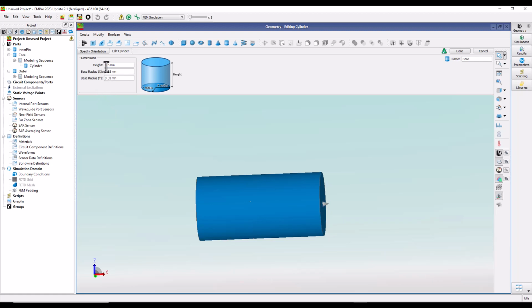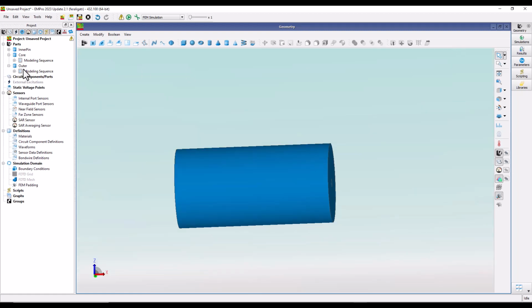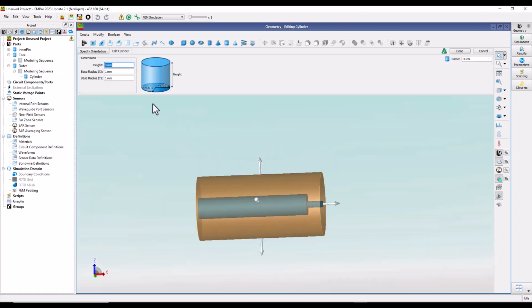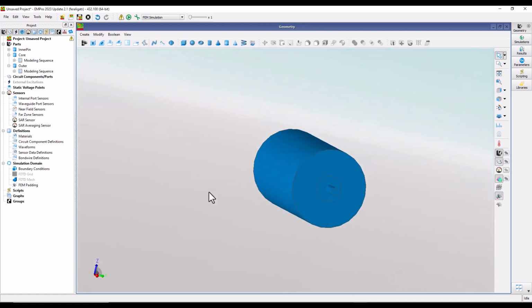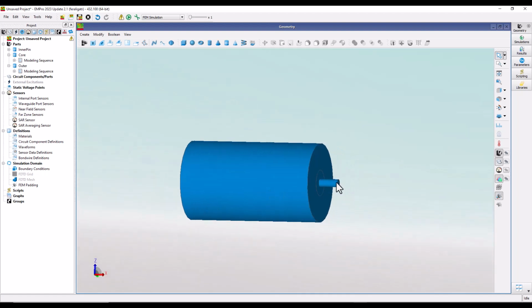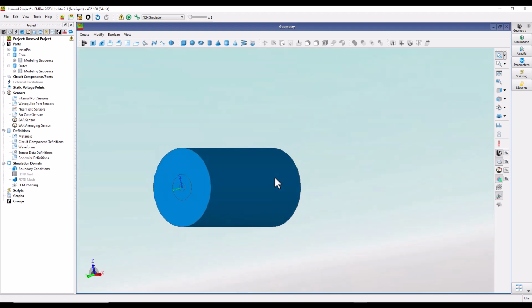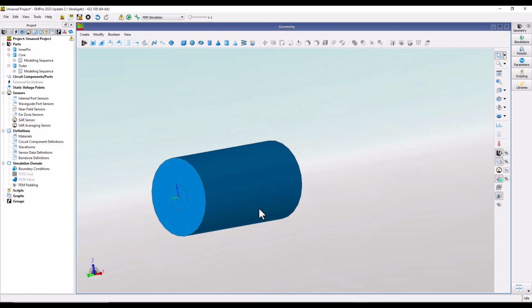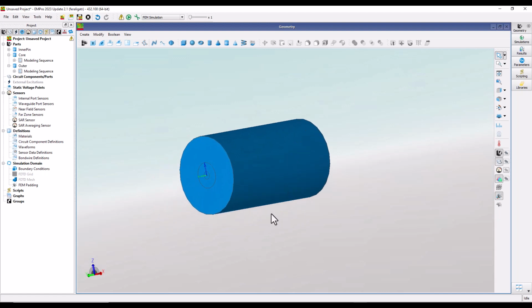But depending upon how much lead you need, either you can reduce it or you can increase the center pin height. And similarly for the core or the outer shell, I'm going to make it 3.5, and now you will have the proper looking object with a lead protruding out. Now finally, I need the mounting flange, and although that flange is not mandatory, it's just to give it a realistic feel.